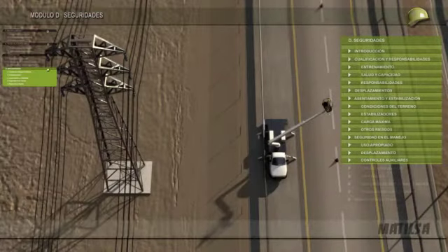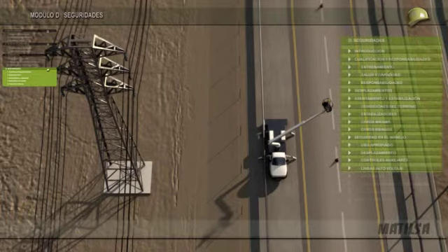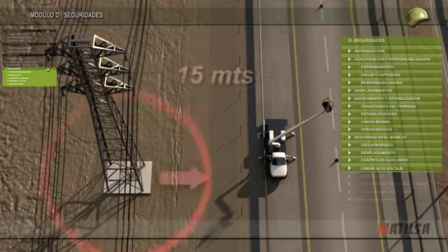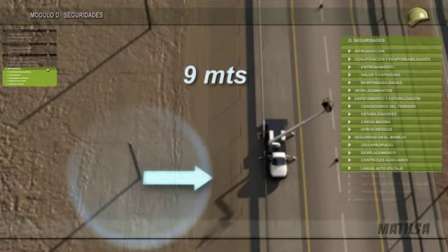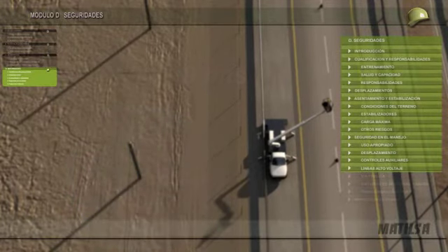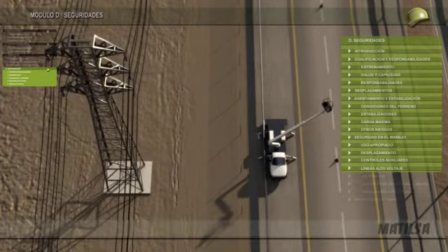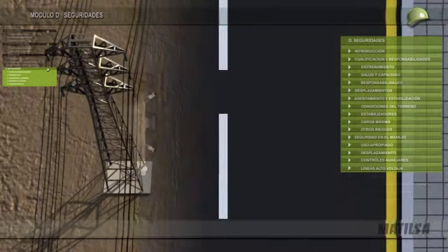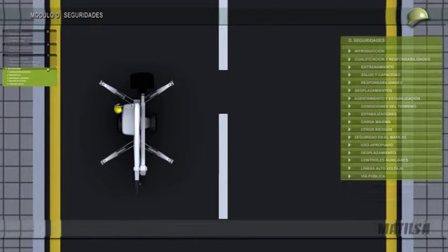Working over high voltage lines. While working with platforms in populated areas, serious injuries may be caused by high voltage lines. The minimum distance that we will keep from a high voltage line will be about 15 meters, and about 9 meters in lines located over wooden poles. At present, there is measuring equipment that is placed in the basket and which constantly evaluates potentially dangerous proximity to high voltage power lines.